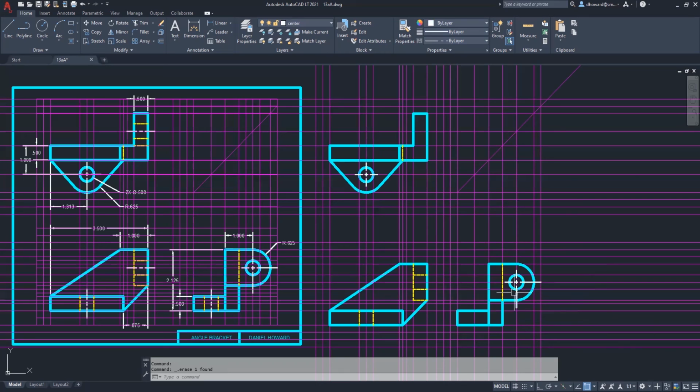I didn't really extend these two lines over here. I made additional line segments. You can see there's one there and there's one there to extend out the center lines. And again, you might have said, well, why didn't you just literally extend it? Why don't you just grab the endpoint and drag it out? That's easier. And the reason is that you lose that nice plus sign in the middle when you do that. So I know we've been doing that in the past, but as we get better and better, we're going to strive to be better and produce better work. Okay, so that's a nice little expert draftsman hack right there for you.